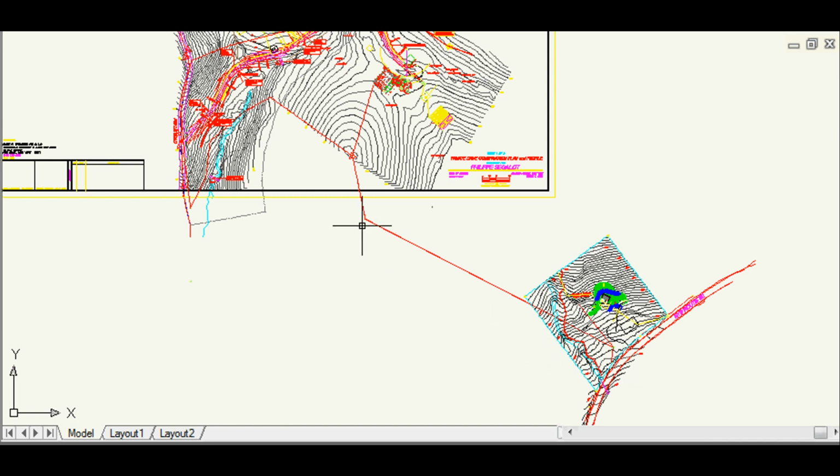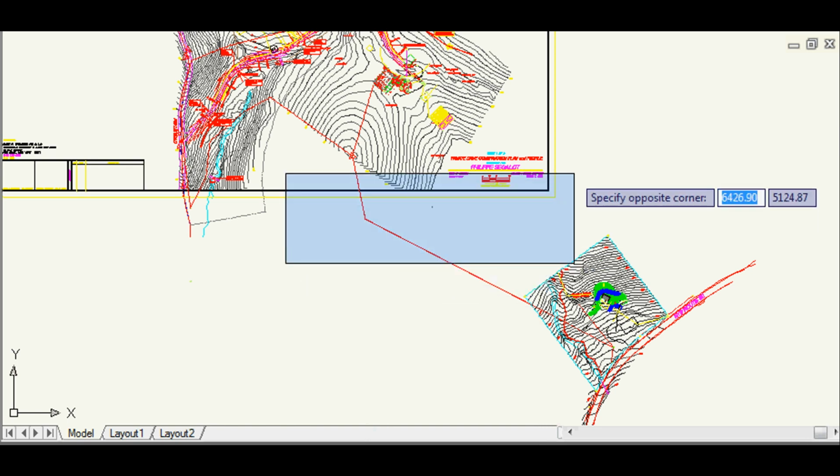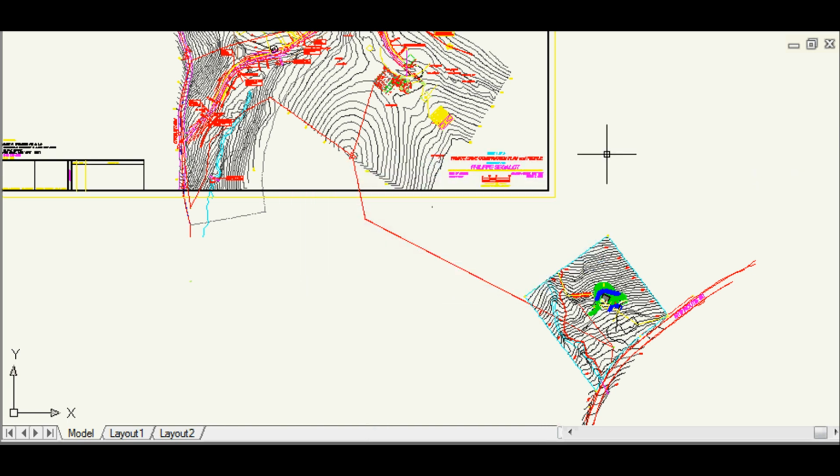Now there's 2 different ways to do control. We can do control with GPS, and we can do control with total station. Now there's other ways as well, but we'll stick to those for simplicity. So total station is ground-based. It's a robot, well, it can be done without robotics, but the equipment we had was a robotic total station. So it was a remote controlled wireless survey gun, which was a really awesome tool to have and use, and very efficient in the field. And the other way to do it is with something called GPS.